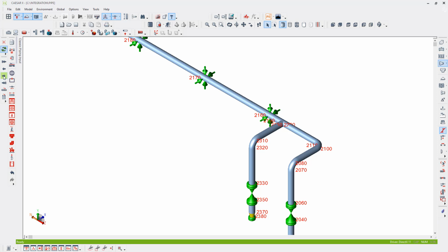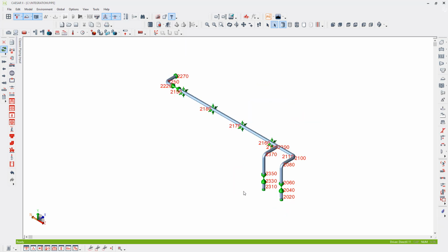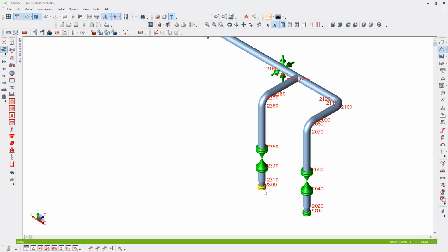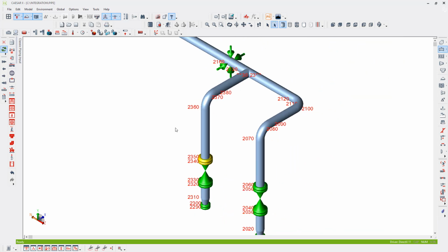As the analyst, I have options here. I can make changes. If, for example, I wish the flow of elements to go in the opposite direction, starting at the pump towards the header, I can set that. I can simply make a selection, right click, and, for example, invert the node numbering. So this now starts at the pump, and as I go next and cycle through the elements, we go towards the header.